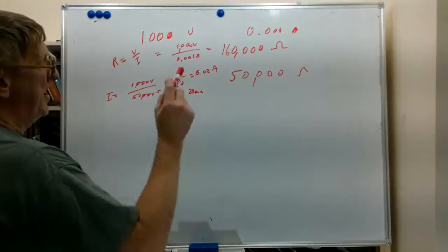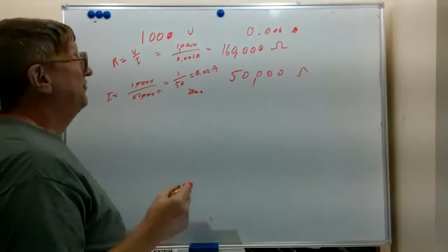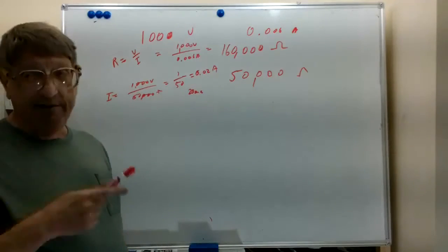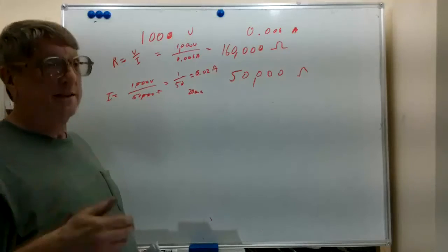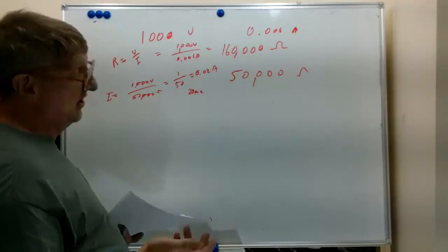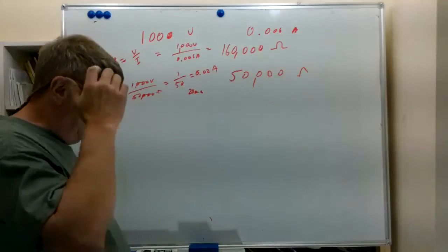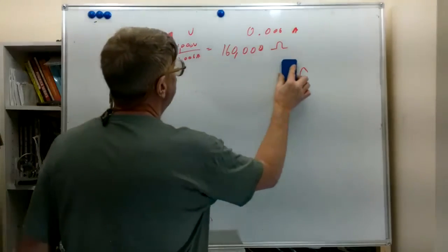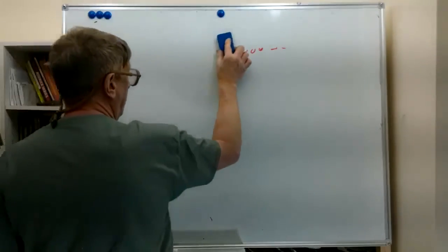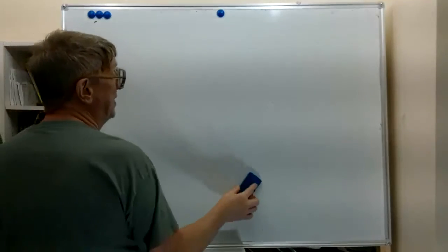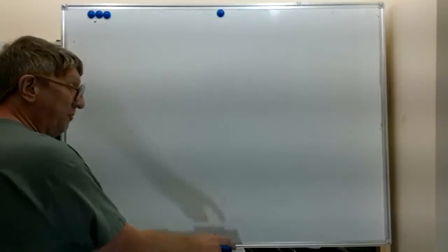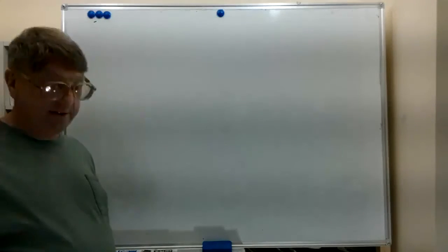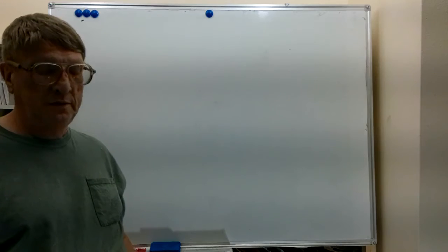So you can very easily be electrocuted and killed by a 1,000 volt supply that is supplying the power output section of, say, a tube type amateur radio transmitter. So when you're working with voltage like that, you want to be really, really careful. If you have to take a voltage reading, it's better to turn the thing off, connect your voltmeter, back away to a safe spot, turn it back on and read the voltage, and then turn it back off before you mess around with it anymore.